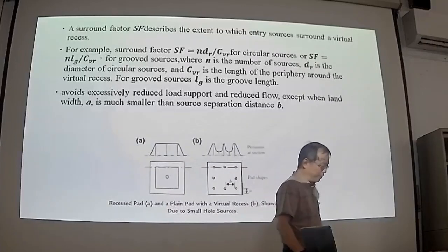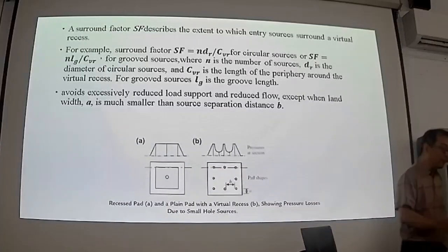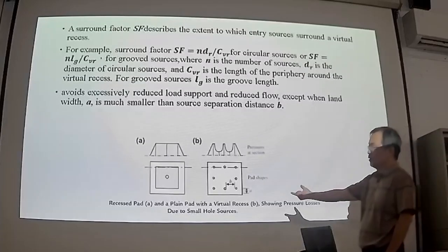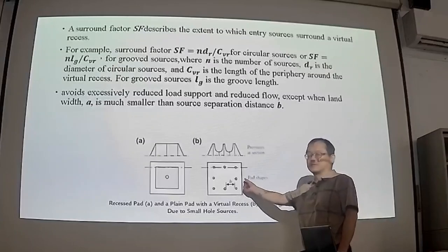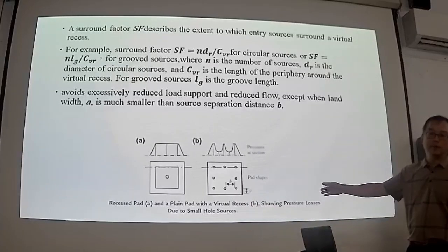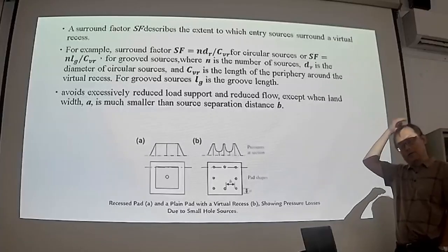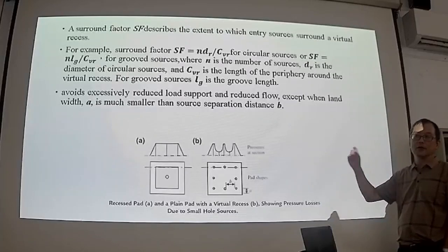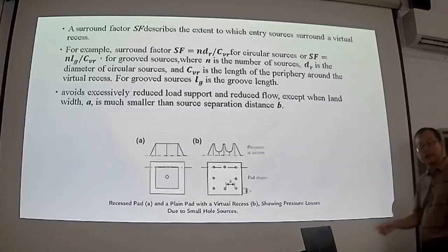In the United States, we have three companies that manufacture porous air bearings. In Japan, at least you have two companies that manufacture. So you should customize the order. You give the dimension of the bearing head and the thickness of the head. For the journal it is the same. You need to give the diameter of the journal and the length of the journal, and also the film thickness during working.